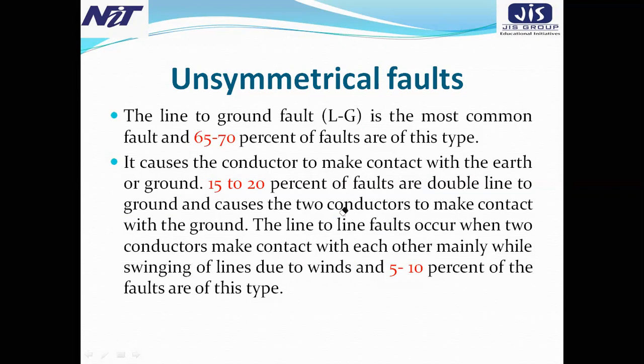So it's a long distance, and the facility of tower is not there. If a tower is there, you can reduce the problem. But if only a 10-meter pole, 9-meter pole is there, it's very difficult to erect an overhead line with the help of only 10-meter length steel tubular poles.